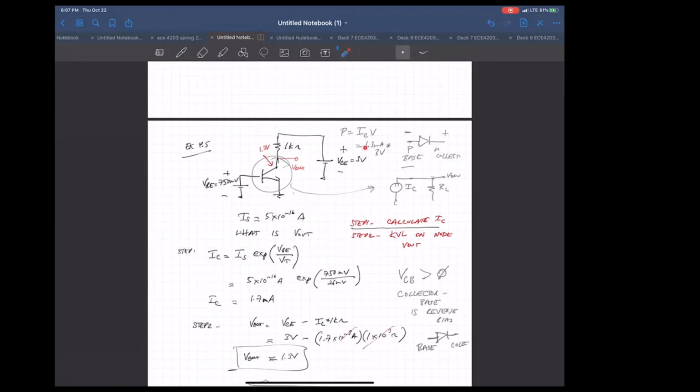So what people will tell you during design reviews, or your manager, is: look, I have 550 millivolts here. You can reduce your power if you bring this VCE of 3 volts down to 3 volts minus 550 millivolts, and you can still keep your transistor in forward bias.